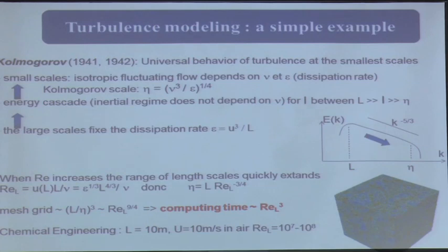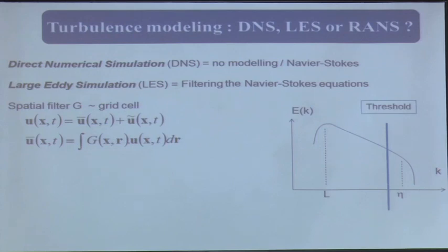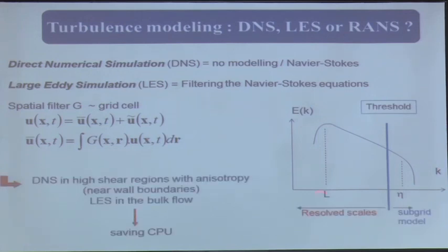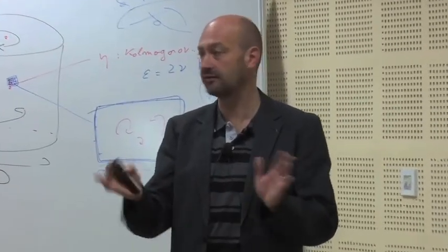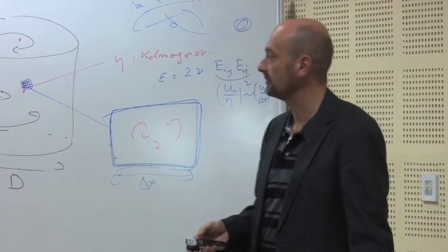And in many cases, when you have, let's say, a bend, or you have a cyclone, you have a complex geometry, the flow is no more homogeneous, no more isotropic, but still you are going to use the only theory which is available to design your subgrid modeling. So you are going to make some errors, and the question is how big the errors are compared to the reality. How far is the turbulence from the real turbulence? Okay, and this is a very open question.